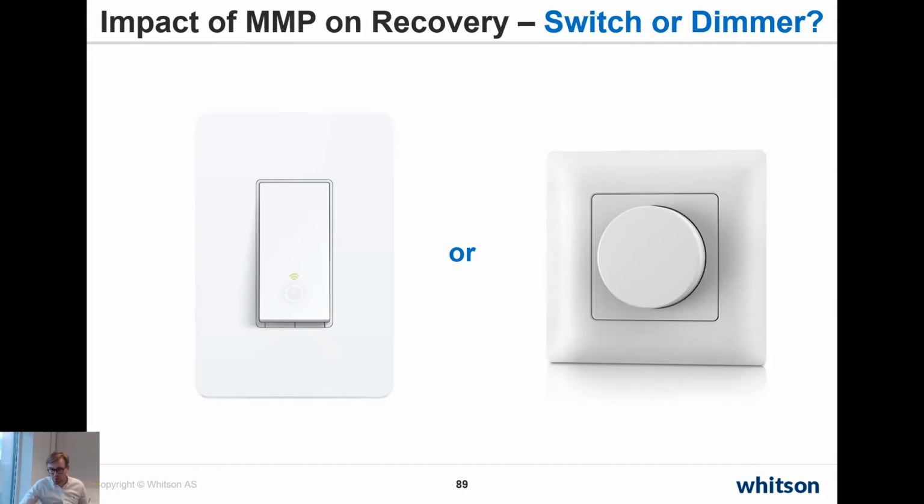Yeah, and that's related to what we see on the screen here about MMP being essentially a switch or a dimmer. So if you do an MMP experiment in the laboratory with a slim tube, for instance, that's kind of state of the art to measure multi-contact miscibility pressure, and we'll talk about that more later. Then what you do is to report recovery factor on the y-axis right here, of stock tank oil, and Stian, please step in if I'm doing this wrong.